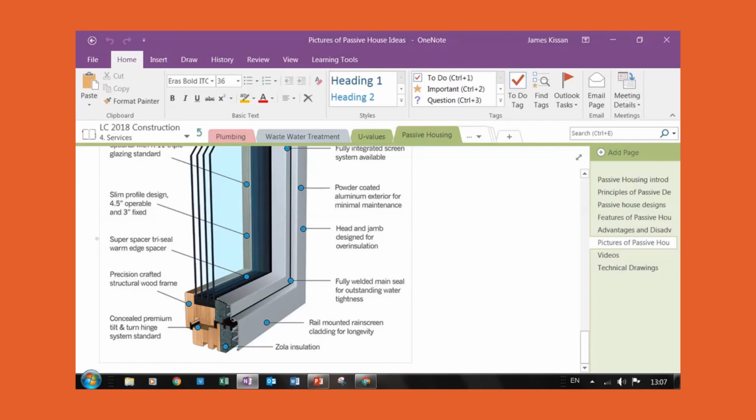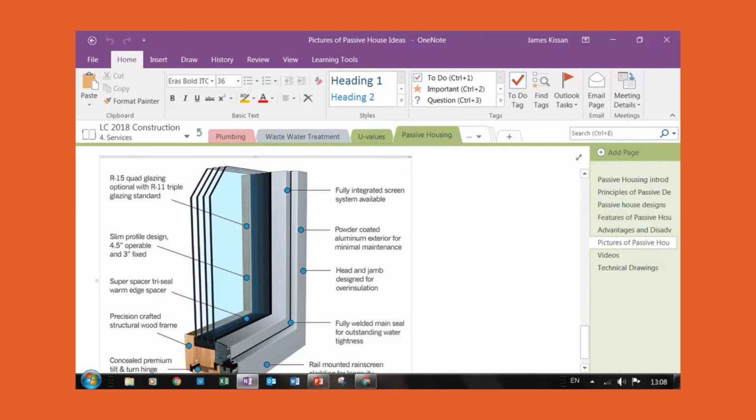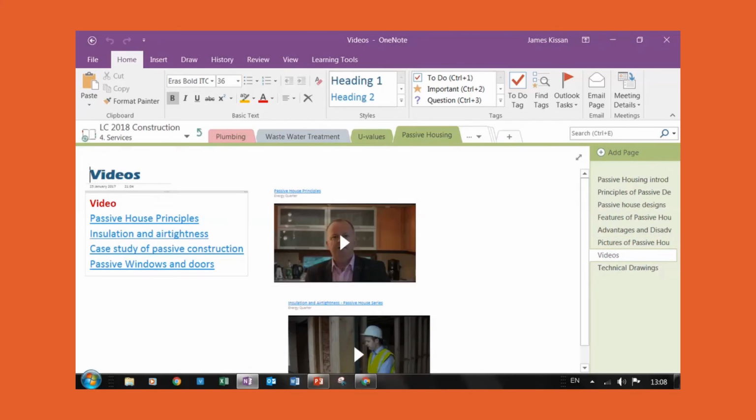And the thermal break in the window frame is the inside of the window, timber that we see, and the outside of the window in some material, some cladding that is weather resistant. So it could be aluminium, could be PVC, could be any color you want. And between the two of them is an insulation material so that any heat that gets into this does not escape out through your windows. And that's where they're trying to come up with the best section possible to minimize heat loss through windows.